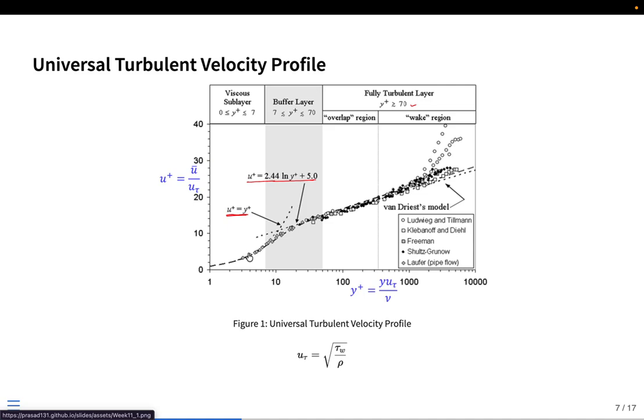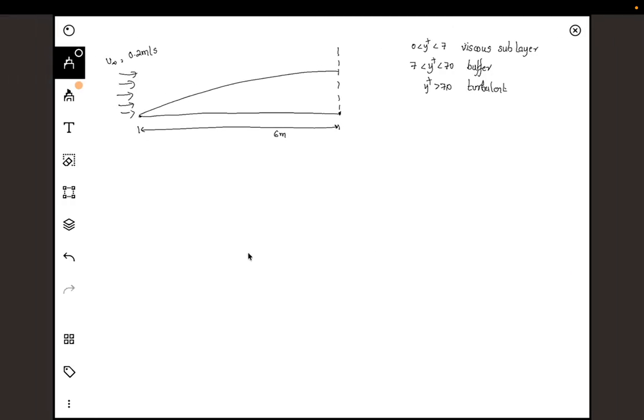So for that, what we are saying is, I want to measure at y plus equal to 2.7. If I want to measure at this particular y plus, the question is what should be the value of the physical distance. The y plus is the local Reynolds number based on a non-dimensional number that we are using. So this is y times u tau over nu, we'll come to that in detail. So what will be the physical distance y? If I want to place a sensor here, what is this physical distance y at which I have to place a sensor? That is the first question.